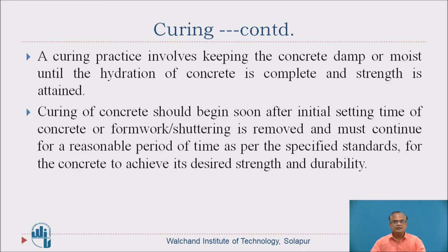A curing practice involves keeping the concrete damp or moist until the hydration of concrete is complete and strength is attained. So, concrete will be kept moist during curing, right? Concrete will be kept damp or moist until the hydration is complete.